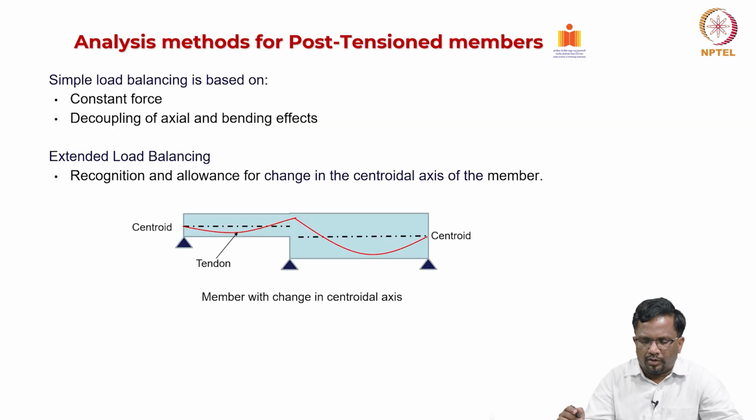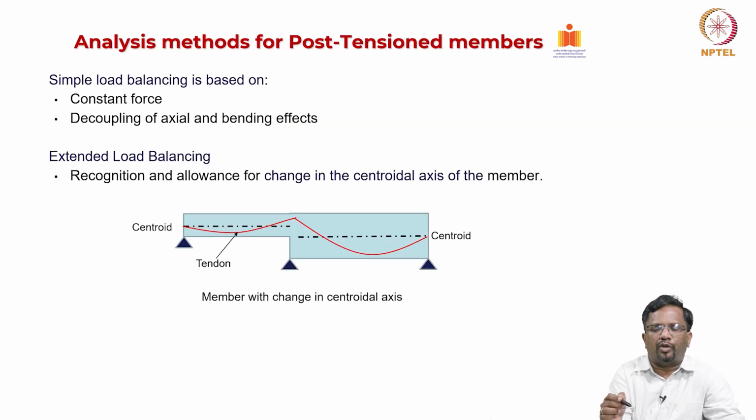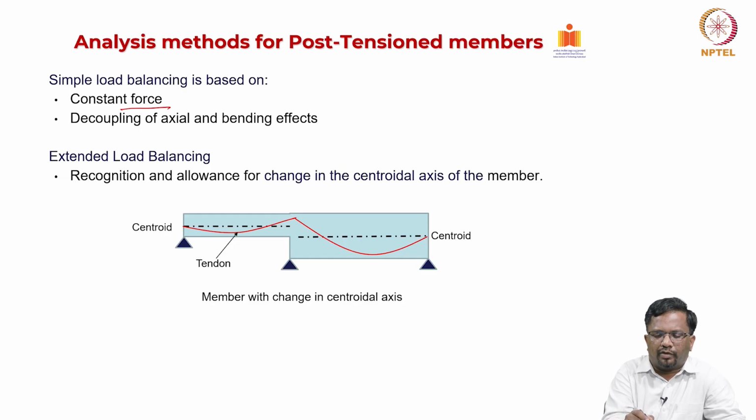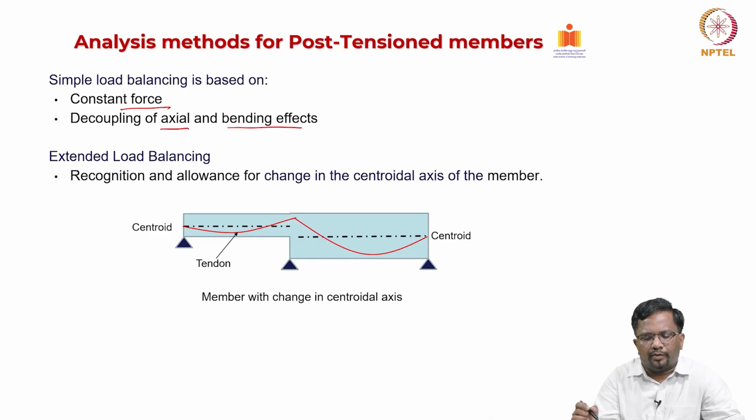Right. So, what is that load balancing concept? The simple load balancing concept is based on the constant force, and we are going to decouple the effect of axial and bending effect. In extended load balancing, we know how to get the balancing loads and moments that are created by pre-stress. We have already studied this in the previous module, so you can look at the previous videos for more information.